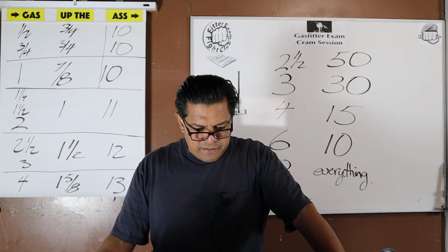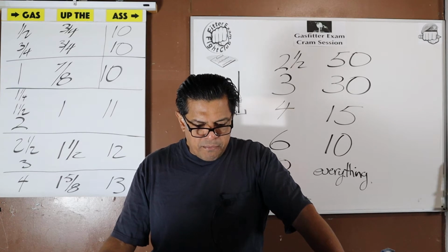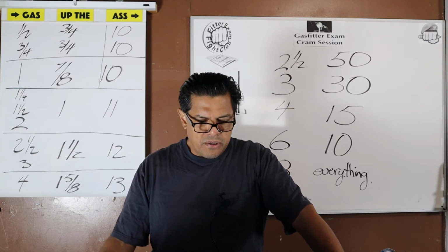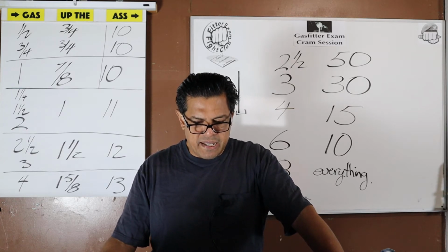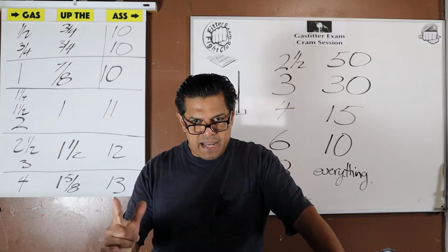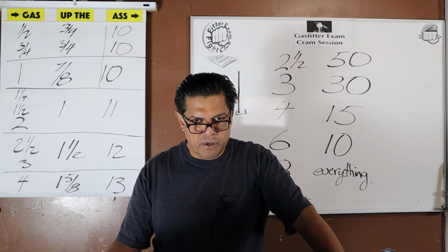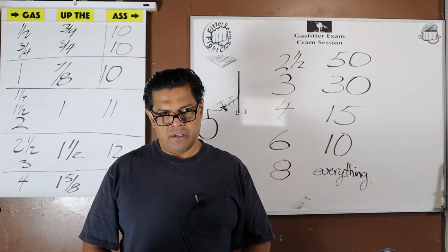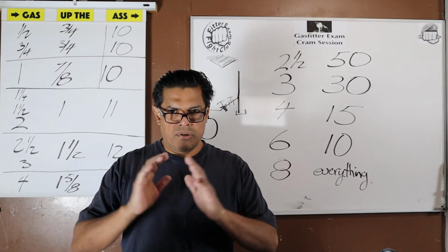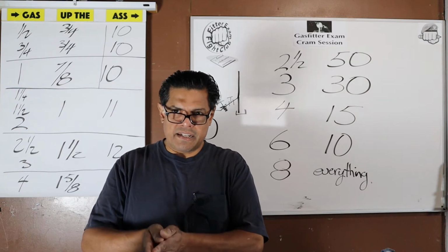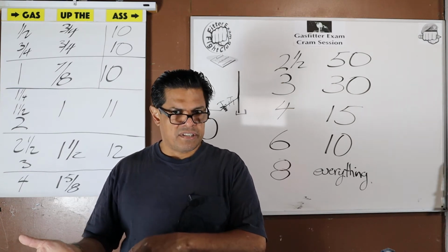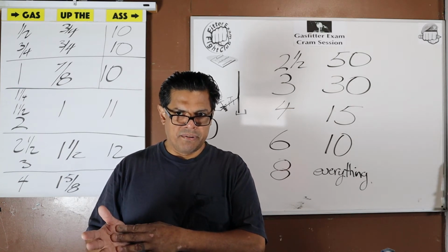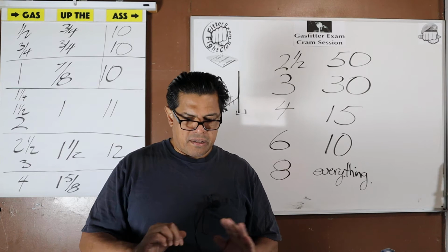Question 5. Except for commercial, industrial, and other large volume use, no gas distribution piping containing gas at a pressure of more than 1/2 psi shall be run within the building. I think I mentioned this almost from day one. The blanket statement is no more than 1/2 psi. That's what we're running. Anything else is an exception. We'll deal with it. You can have pressures higher than that in building piping, but that's an exception.